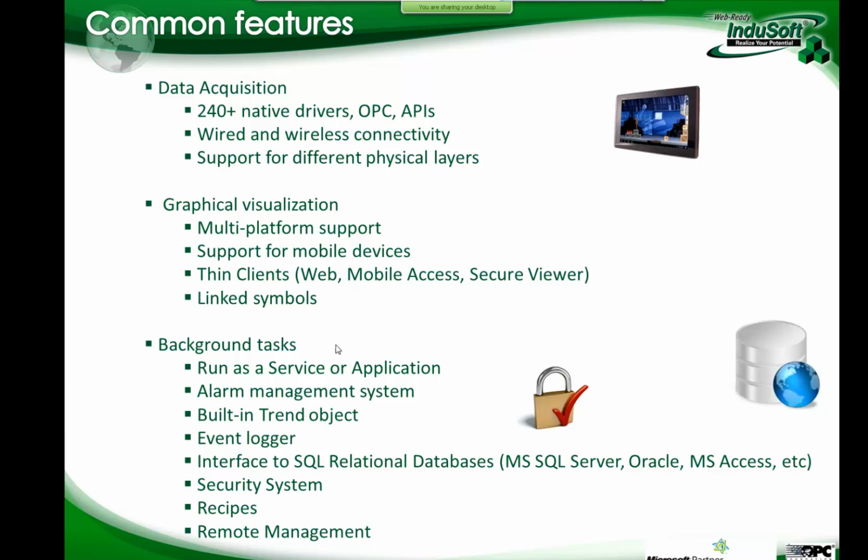And as background tasks, we can run as a service or as an application. So running as a service can be very interesting for data acquisition. So if you have a project and you're gonna have the communication driver acquiring data, you're gonna build trend charts, you're gonna have thin clients, you don't even need to log on to the computer. You can configure InduSoft to run as a service. Okay, and then use web thin clients to connect to that service.